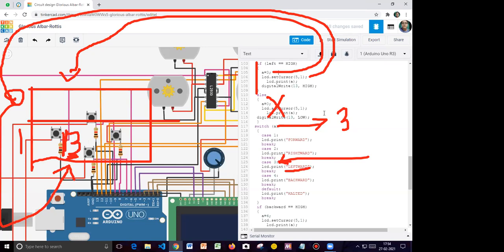In order for you to print the cursor, there is another command. When you set the cursor, it will be there at 5 comma 1. And since you are printing lcd.print of a, that a value, 3, is printed at 5 comma 1. What will the LCD automatically do? Since it already knows that a character is printed at 5 comma 1, it will automatically increment the cursor to the next position, 6 comma 1. So 5 comma 1 is your column comma row. Once it has already printed a character there, it will increment the value. So it will be 6 comma 1.